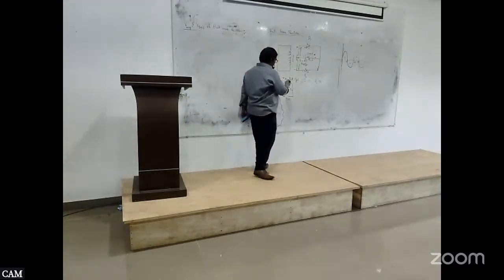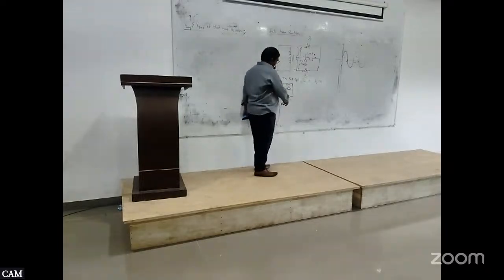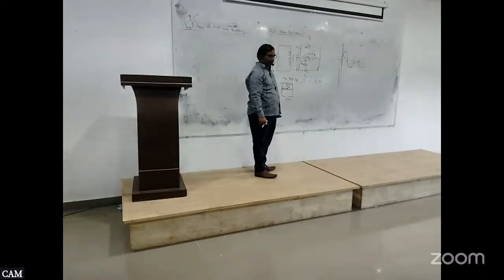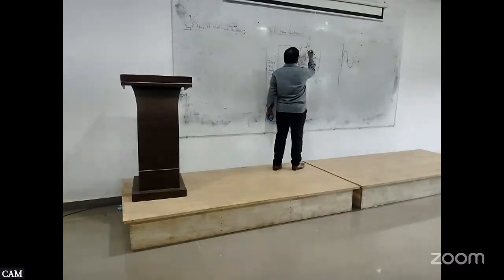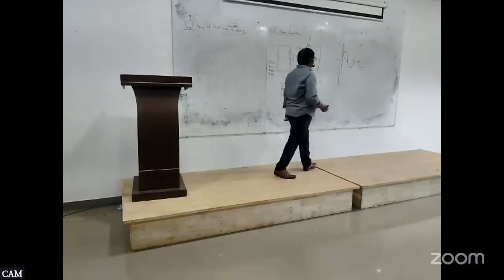So during the positive half cycle, what happens? Current will flow from D1 to the load. What happened to D2? D2 is off. There will not be any current flow. The circuit will become D1.